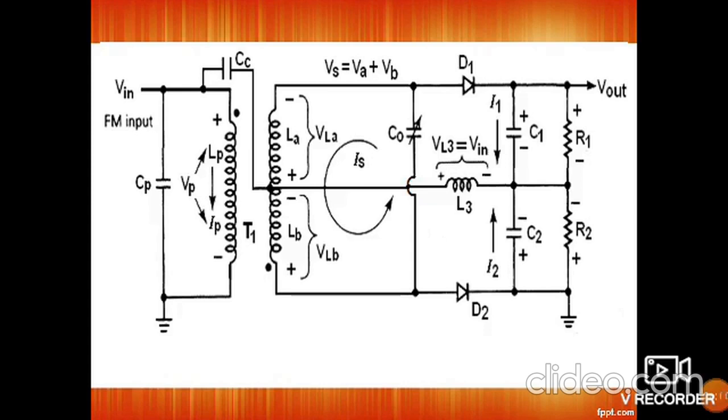So here we have one carrier center frequency. Inside this capacitor Cp, the carrier frequency, termed as Fc, resonates with the frequency of the transformer. The Foster-Seeley discriminator utilizes the principle of FM detection or demodulation. This figure shows the Foster-Seeley discriminator as an FM demodulator.